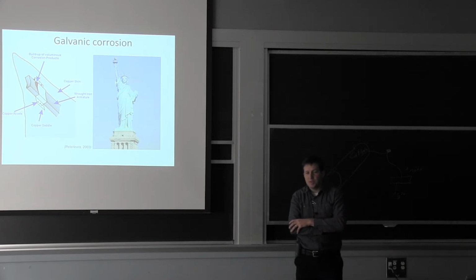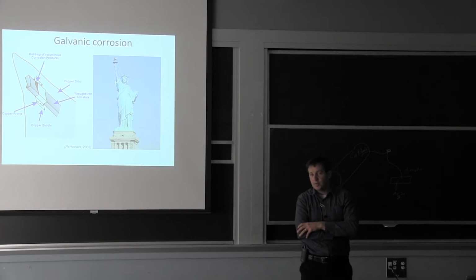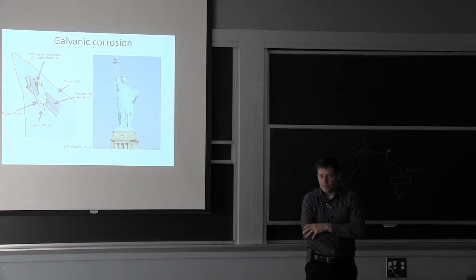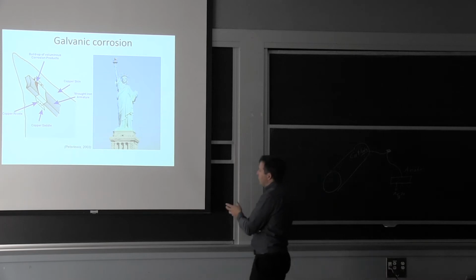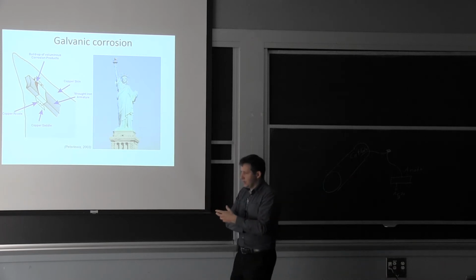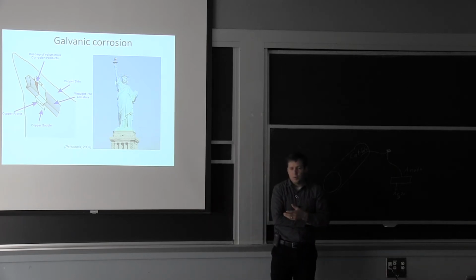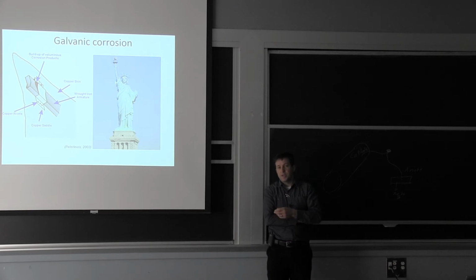One situation of dissimilar metals that you don't have to worry too much about galvanic corrosion in general is between aluminum and steel. So aluminum and steel would be a little bit like copper is to iron. So the iron doesn't get corroded, the aluminum does, but the only advantage is if the aluminum is passive, it will be able to resist the galvanic couple.